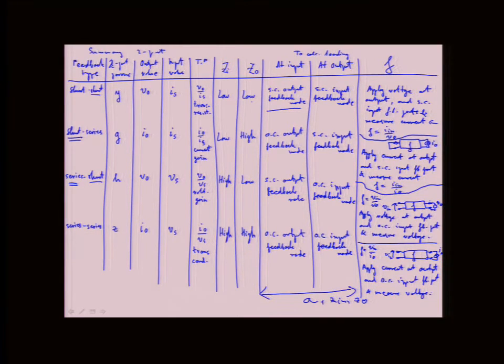So that still doesn't tell you how to do it, though, right? So you still have to look at the types of feedback at the output and input and figure it out. I think a more involved thing than this table is actually when you do the real circuits, as we said, you would have to go in and always in two-port map, locate where the feedback is and figure out how to turn inputs and outputs on and off and how to map it to two-port and do it. Okay.